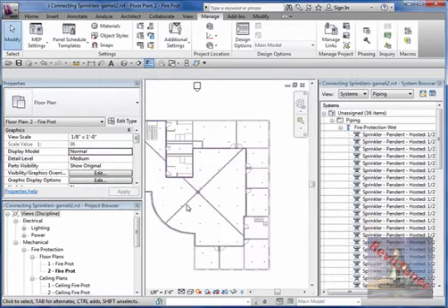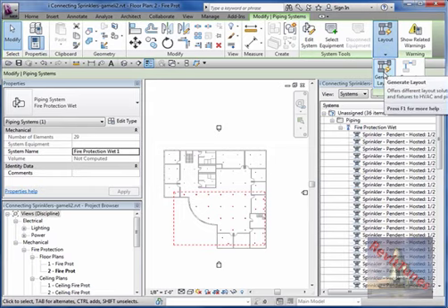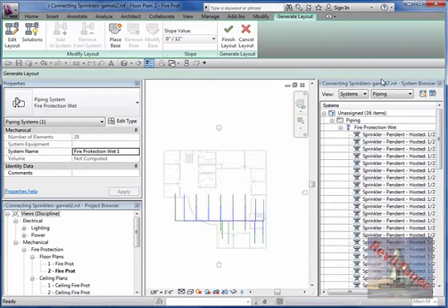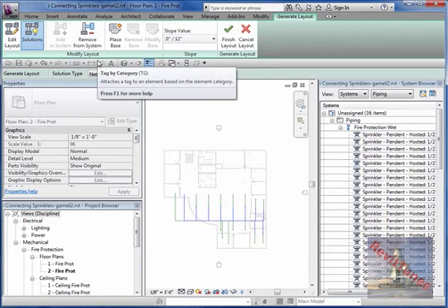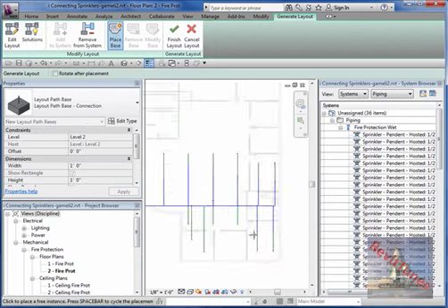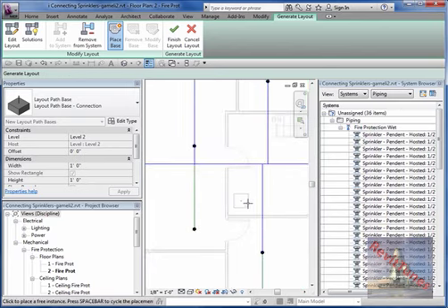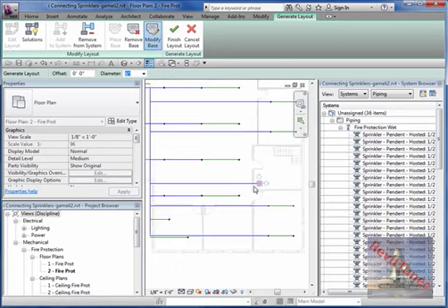Okay, so I will hit tab on top of one of the sprinklers. So I'm selecting my whole system. Now I'm going to say I want to create a layout of my piping. So this icon has 2 icons. Now it gives me all these options right here, new tools. Again, I could add or remove more sprinklers, and now I'm going to place what is called a base, and I'm going to put it here. Basically, this base is like an outlet. You see how instantly it connects like a main pipe to this main branch.